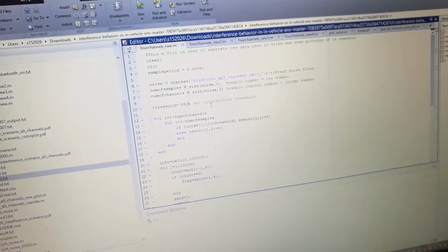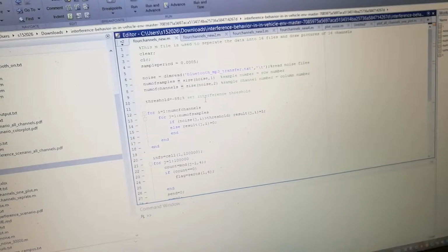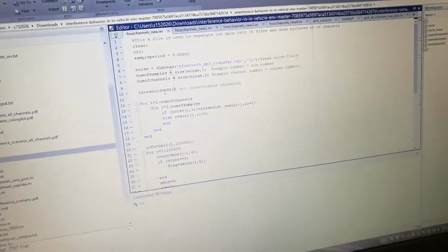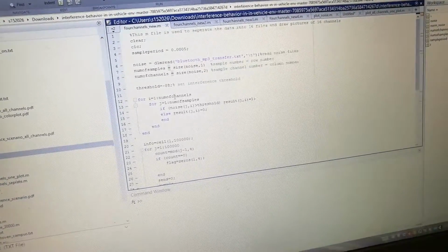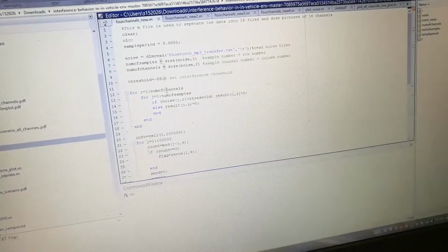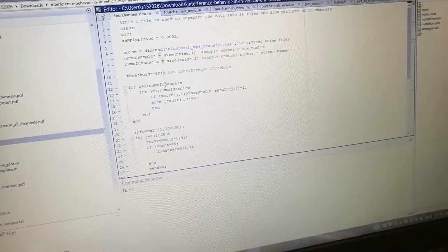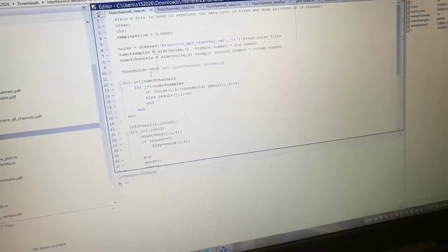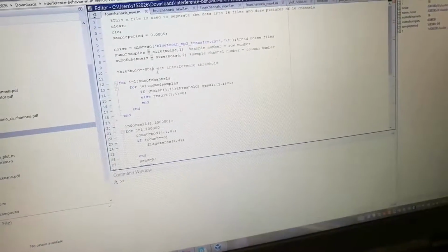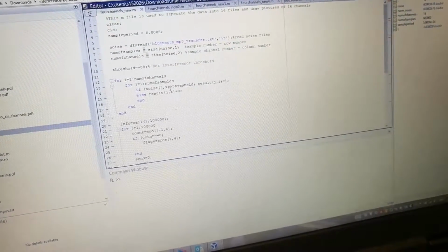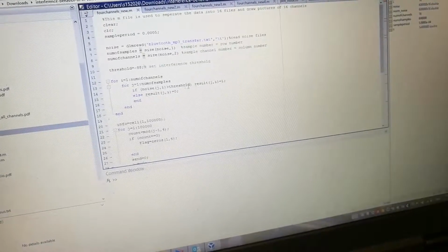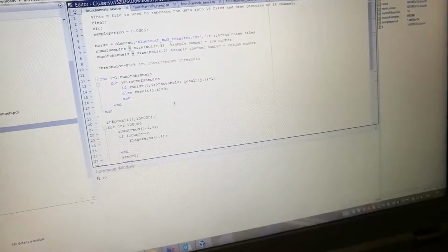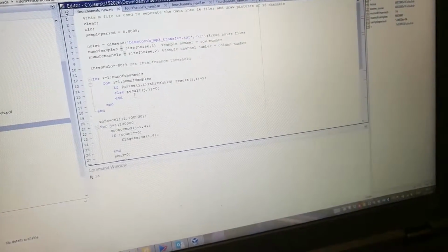After that, we use a MATLAB program to process the Bluetooth audio streaming dataset. The threshold and transformation values are defined to eliminate environment noise and represent whether interference exists or not at that time respectively. For example, we set the interference threshold to -88. If the power level of the original data is higher than the threshold, it will be considered as interference, and the transformation value will be set as 1. Otherwise, the transformation value will be set as 0.